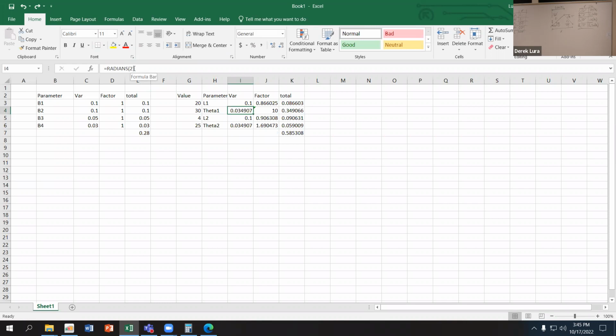So you can figure out which parameters inside your design are important for either maintaining or destroying whatever the tolerance you need is. The implication there is if you have parts where changing the parameters of the part does not change the overall performance, basically the thing you're trying to preserve, that's a justification for having a large tolerance on that from a manufacturing standpoint, which will save you money. So it's about isolating where you think the most important aspects of the design are, so that way you can not spend a whole bunch of cash. Does that make sense? Any questions on that? Again, pretty straightforward.